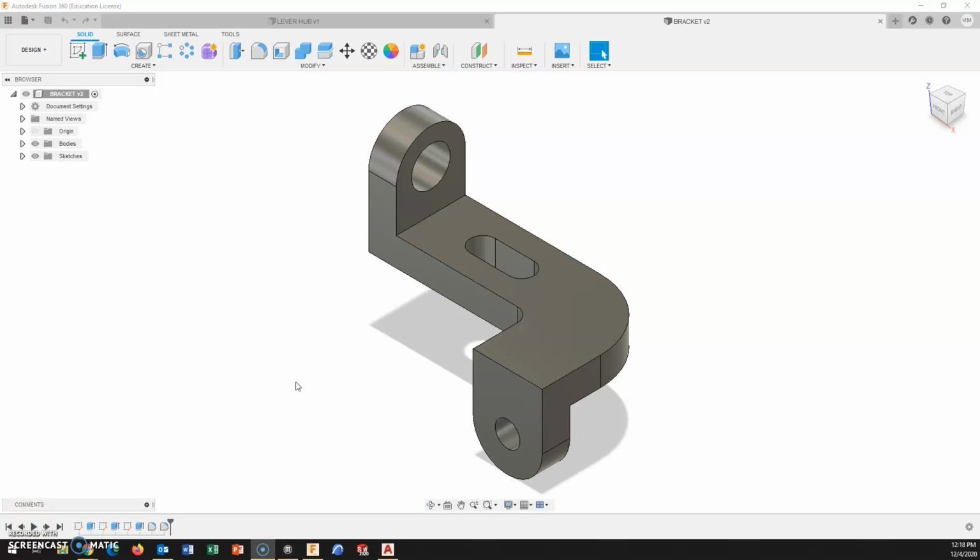All right, drawing for the bracket from problem set 4. Even though you may have used the fillet tool to round these two corners off, these are structural fillets. They are not casting fillets, so we are not making a dimensioning note. We will need center marks for the slot as well as the holes, and then center lines for the holes.